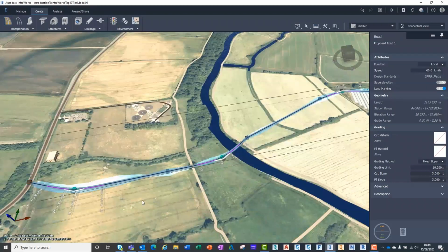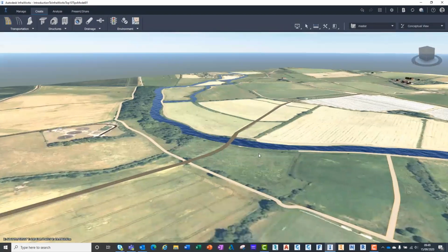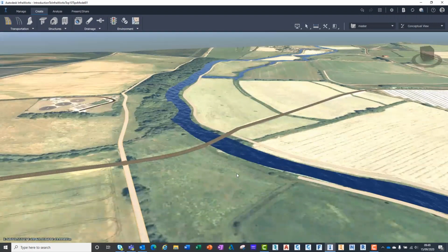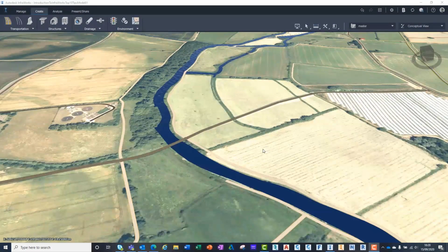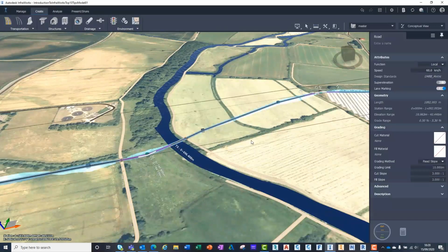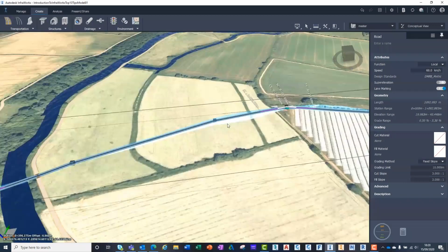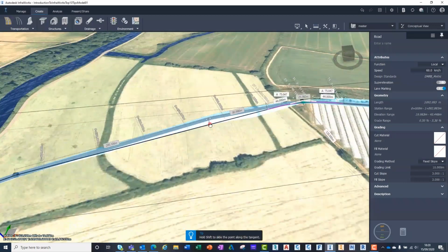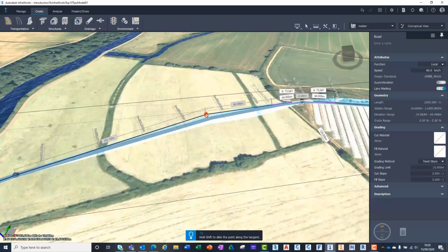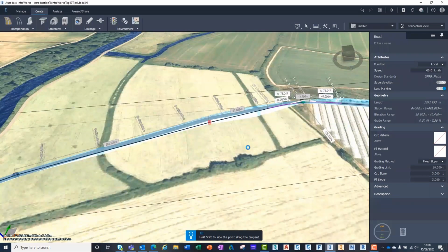We've now completed a preliminary road model. In real time, this would take a user less than a minute. Now that we have created our road, we can manipulate the model in the horizontal plane by dragging the nodes to alter the alignment how we want it. Where radii occur, its movement is restricted so that it stays within the confines of what is trafficable.